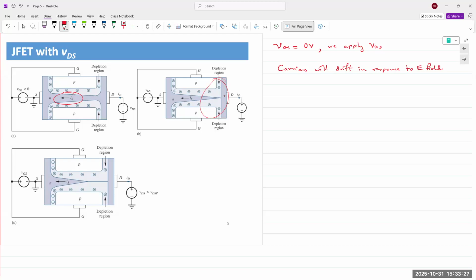If we flip the drain and source terminals, then we would see the effect on the source side, not on the drain side. But on the drain side, it is starting to merge. And when it gets close to merging, we have a similar pinch-off effect. And one caveat to this is, of course, all of the dimensions in here are exaggerated just for effect and for explanation purposes.